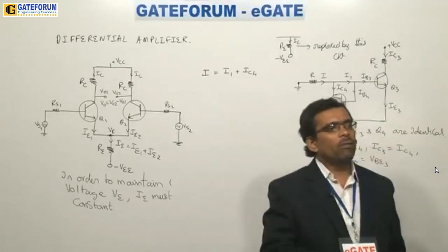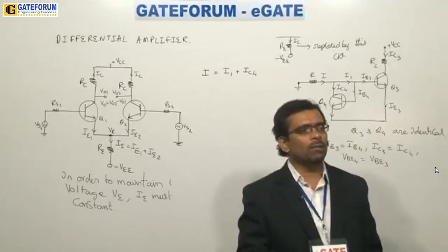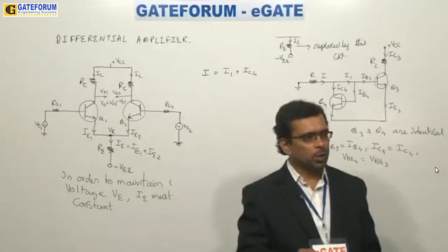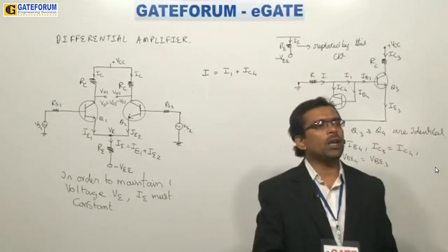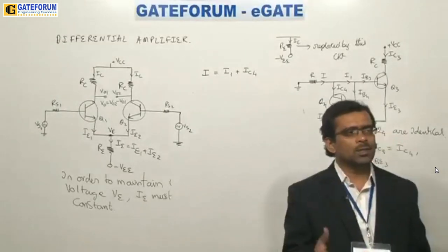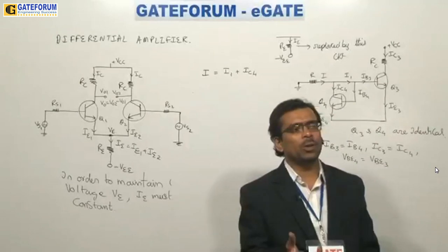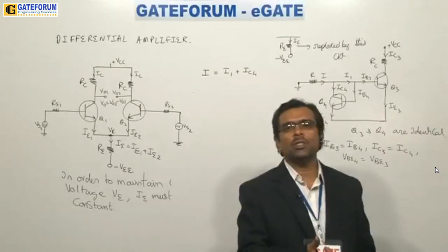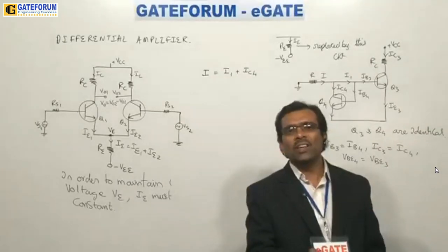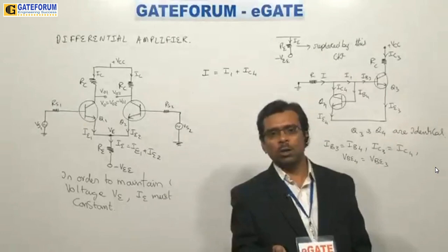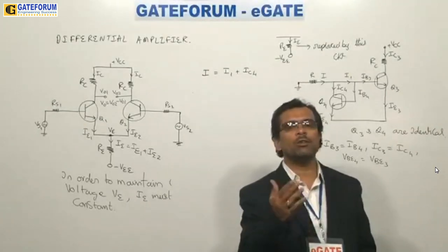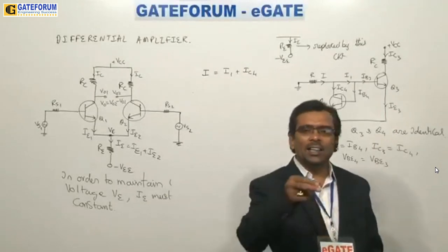Right. So next, Aman from Delhi. When one transistor of the op-amp goes into cutoff, then the output should be VCC minus V01. Yes, it is true, but V01 is varying, so the output should vary. Yes, it will vary for sure. But what happens is that the V01 value, when you compare with VCC, will become very small, because that signal will hardly come to 1 volt. VCC will be nearly 15 volts. Due to that reason, the transistor has great chances to get into saturation very easily here.